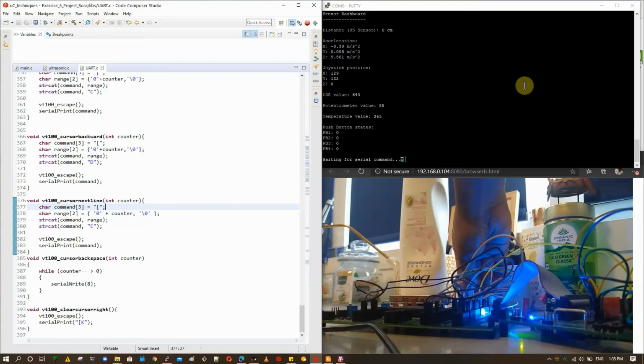Now let's look at the joystick values. Let's move the joystick Y position to the extremity, and as you can see, since it refreshes at a slower rate than the rate of change, we don't see an instantaneous change in the sensor values. Similarly for the x-axis, it does the same, and also for the z-axis. The basic value when the joystick is at the middle is 255 by 2, which is approximately 127.